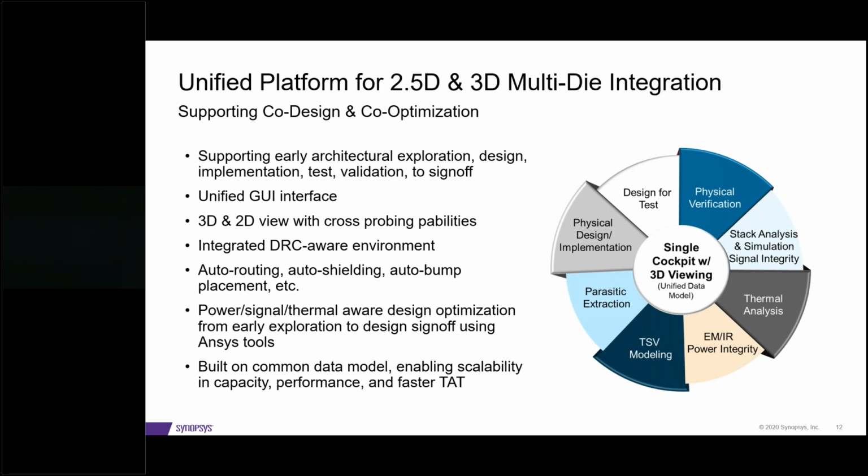So for example, I can bring the GDS from one vendor. Any of these dies can be designed using different tools. But in order to fabricate those chiplets, you will create a GDS2 format or OASIS format to send to your fab. So that format is standard.